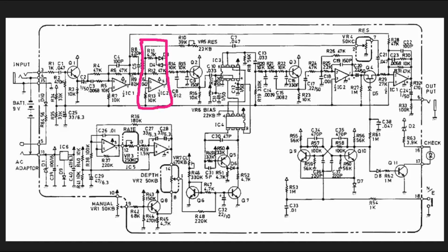So our signal is coming in on the inverting terminal, and we're biasing the op-amp up to VREF, and we have a signal that's going to be coming from this direction also. So this op-amp here is working as a summing amplifier. And in the feedback loop, we have a resistor that is helping to set our gain, but we also have these anti-parallel diodes here with a resistor.